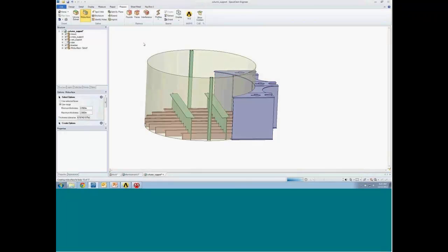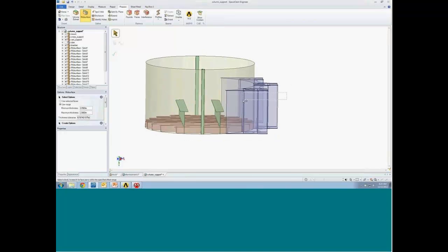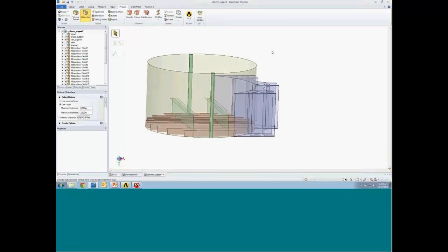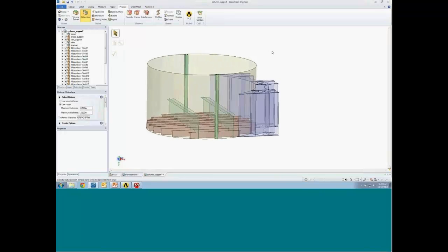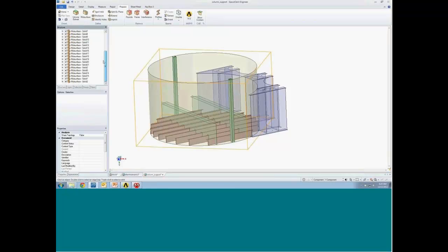Click the green checkbox, and we extract out the mid-surface of all those. That's very fast. Now there's a bunch of them that I missed. That's okay. I run through another operation and do the rest of them with a simple box select. And I have them all done. Now that's just the mid-surfaces. They all show up in a nice, clean component in your structure tree so that you can organize them, turn them on or off, do whatever you want with them.